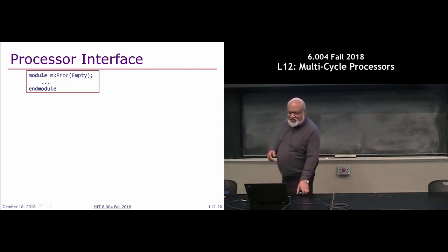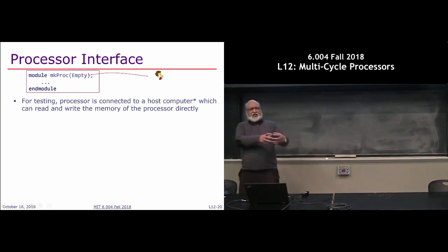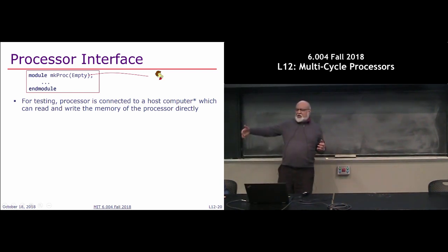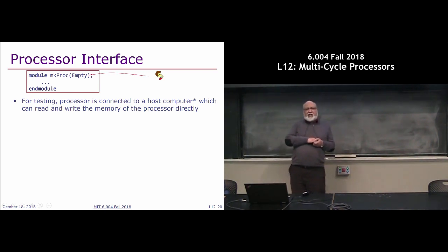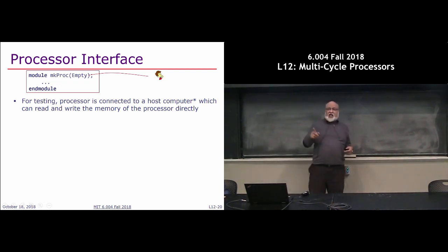The way we are cheating in this is for processor designs is, for testing, processors are always connected to some other processor, right? Because this is the design you're doing. And so what we can do is this other processor by some magic goes and loads the memory of the processor you are designing, sets the PC to 0, now it gets going. How do we know it has ended? Because when it stops, it goes and writes in a particular location in the memory, which I'm always watching. I'm saying, somebody wrote it, they're done. Simulation stops the moment somebody writes into that location.